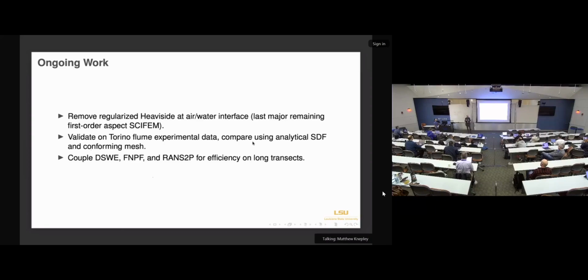You get instability because of added mass, and that's exacerbated when you have very low accuracy on your forces themselves. So I thought we had to get both right before we could finally do floating structures well in wave-driven environments. Now those interfaces are man-made structures, so they were simpler.